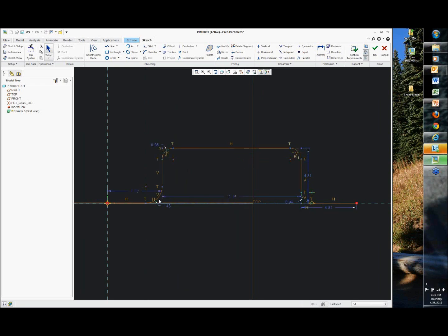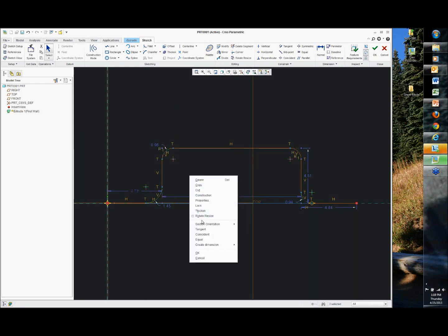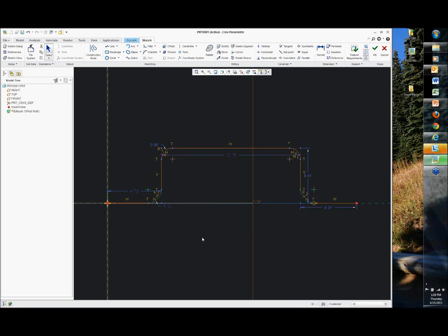And this one equal. And the reason why they're not all equal is because when you're talking about sheet metal, you're really talking about the inside radius being what's important. That's what die they're going to use to actually create this. So for me, I purely want to make sure I'm driving my design to the manufacturing processes. So I've made my shape.